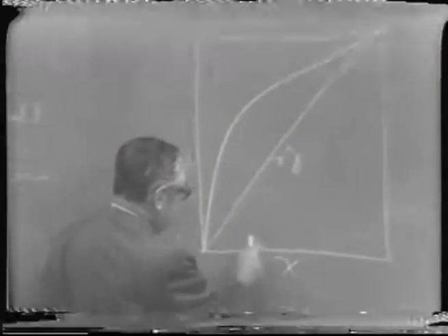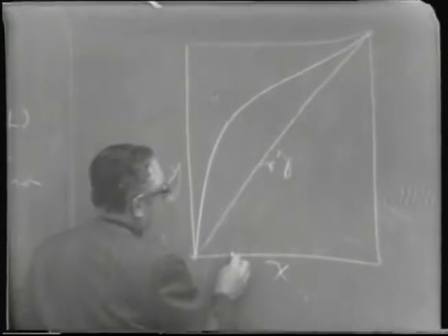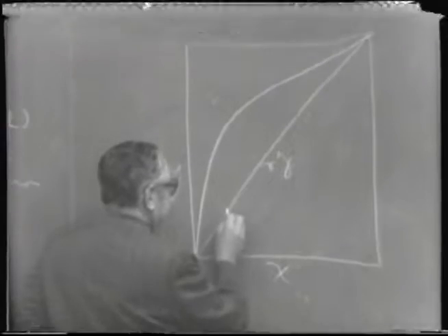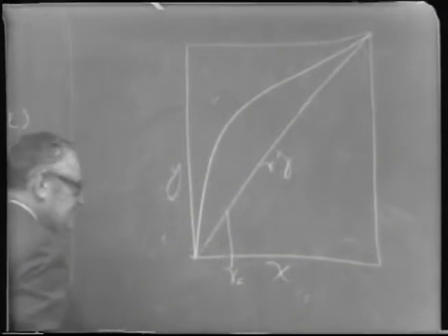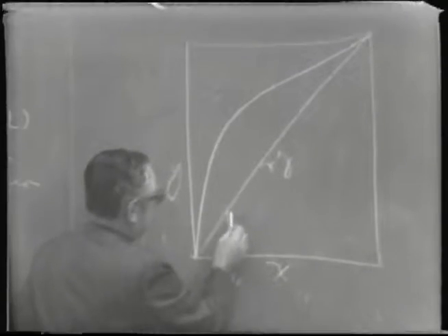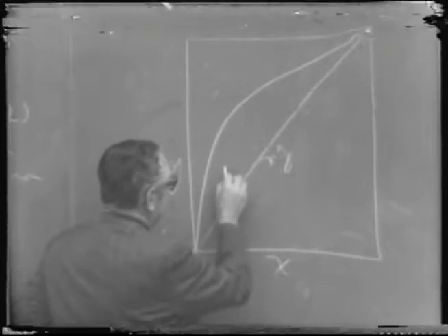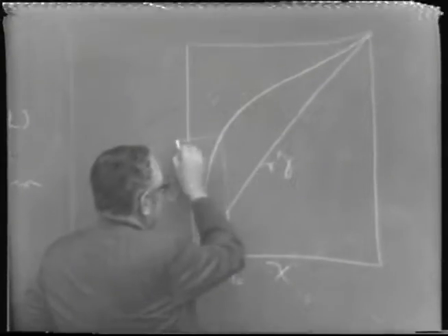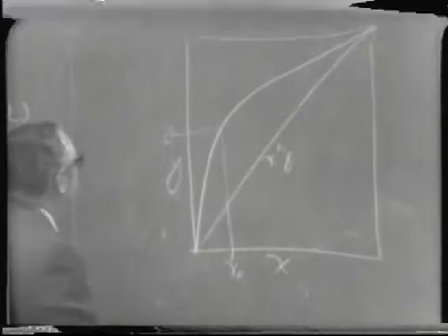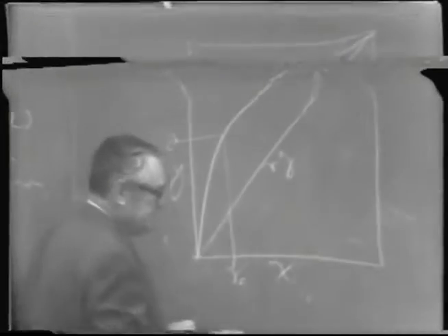Well, what happens if we introduce this feed into a distillation system and vaporize it under equilibrium conditions, or under complete equilibrium conditions? The curve tells us that the vapor given off is given by this value here, which we might call Y1 if you want to, since it's the first stage of vaporization.